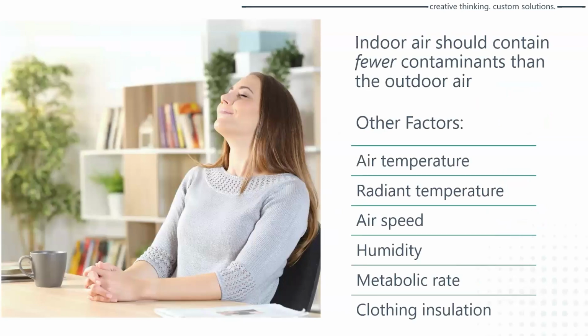Okay, so 80%, right? Keep that in mind. Indoor air should contain fewer contaminants than the outdoor air. Why is that? Well, we've got modern building envelopes that have filtration, HVAC systems pulling air from outdoors, passing it through filters, it's being conditioned to a temperature and relative humidity and delivered to the occupied areas.